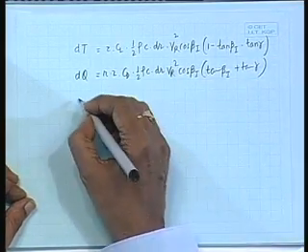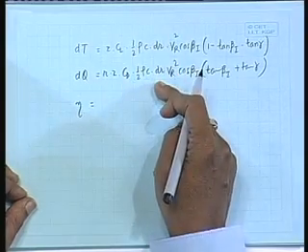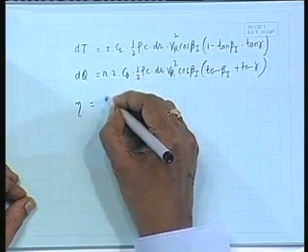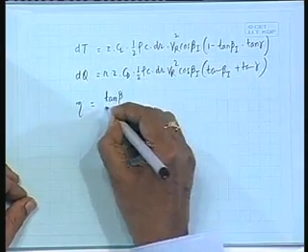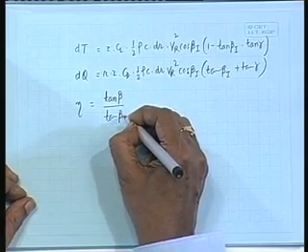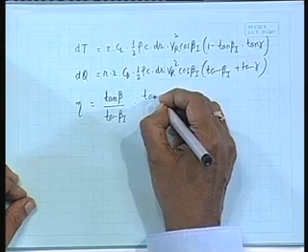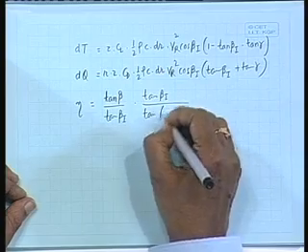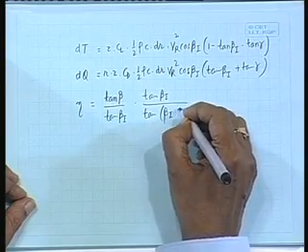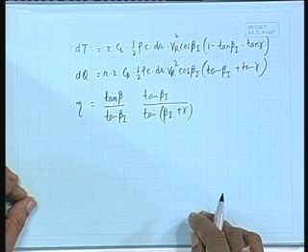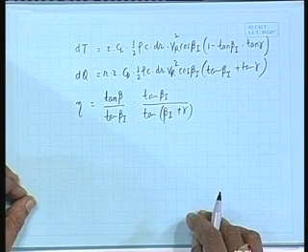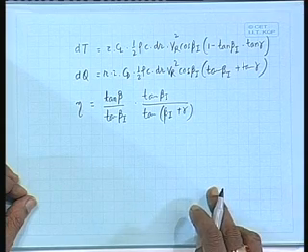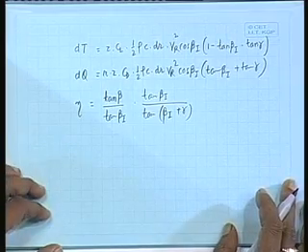So, efficiency we can now write in terms of dT and dQ as we have written previously, and it can be shown to be tan beta by tan beta I into tan beta I divided by tan beta I plus gamma. Sorry? We can, but we will not.